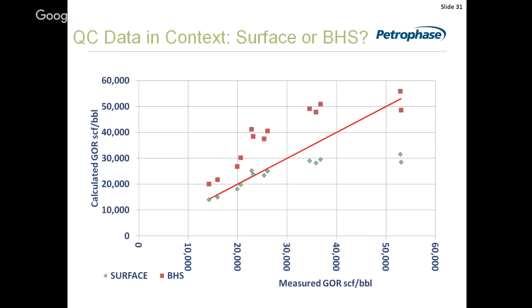So it's telling us that if we flow much faster, we're not going to keep that up. We will lose condensate. So what this tells us is two things. One is that the separator condensate compositions are correct, and that the bottom hole sample was incorrect, but it also tells us how we can manage our wells and the production, the condensate that we can get from that as a function of the rate. So this information not only tells us the fluid, but it helps us for the field development.